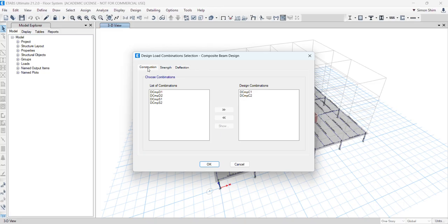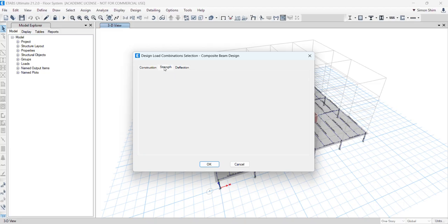Before the concrete hardens, the beam and deck are running, supporting all the weight. That state we call the construction phase. The steel beam should carry the wet concrete weight. So that is a phase where we need to check the strength and deflection.